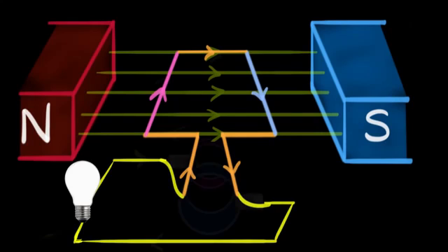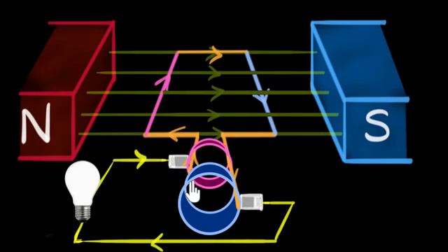It looks somewhat like this. So basically we have two metallic rings, the pink one and a blue one. And what you may not make out from my diagram over here is that each ring is connected to one wire only. So the pink ring is only connected to the left wire and the blue ring is only connected to the right wire. And these wires are connected to carbon brushes, which is also conducting. And they are just touching these rings so that there is a metallic contact, but they're not stuck to it.